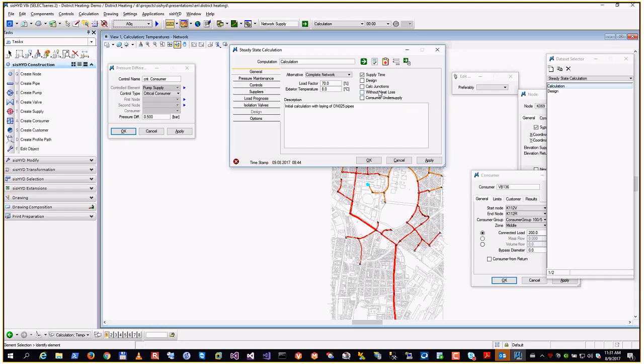If we iterate and the temperature difference gets too small, it means high mass flow. High mass flow means that the water does not cool down, so it's alternating between values and does not find a solution. There are typical reasons for that, and you can find those spots easily when you turn off the heat loss computation.